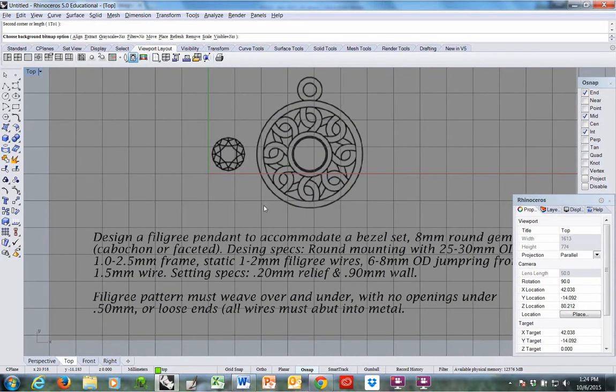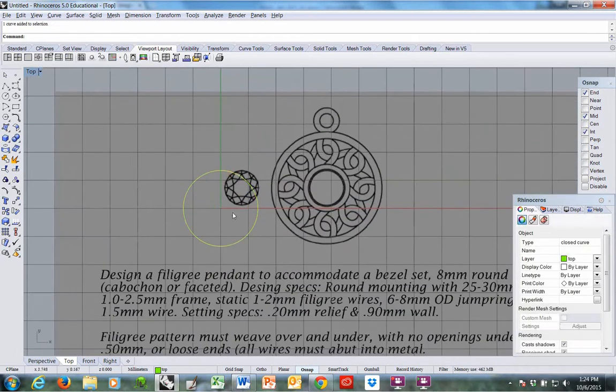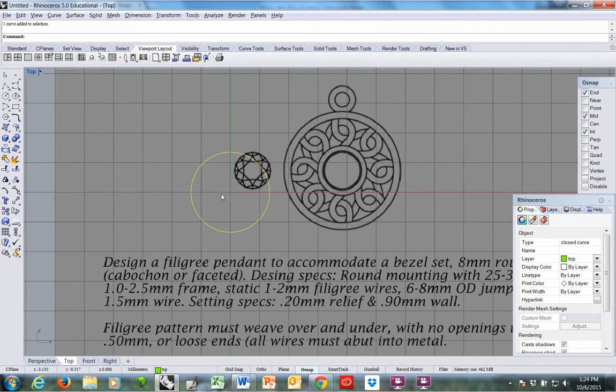Alright. Going to now center this and bring it to scale. Do that by first drawing the circle that I want it to fit into when it's all finished. I'm going to make it a 27mm diameter circle. I want to make sure diameter is checked, and that I type in 27. This provides me the reference points that Rhino is going to ask for on my construction plane.